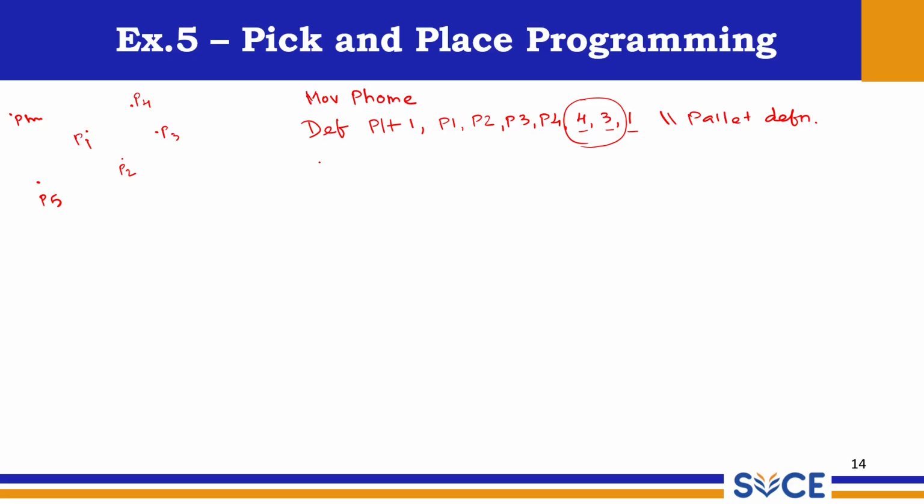So now you know how to go ahead, that is P5. The first step is we are doing palletizing. Therefore MVS P5, alpha point, minus 100. Now the robot comes nicely and is on the alpha point of P5. So it is at the safety point. Now M_out 15 is equal to 0.